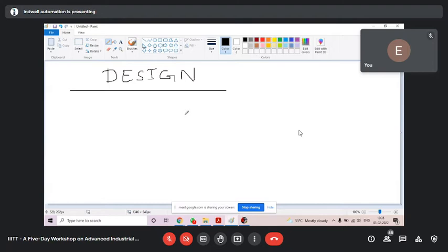You select whether this start is for Mitsubishi, Allen Bradley or for Siemens. Then it will ask you, okay, now you give the address. Then you can give X0, X1. If it is Allen Bradley, then it will accept I:0/0 like that.